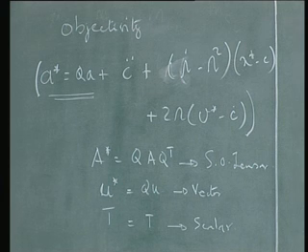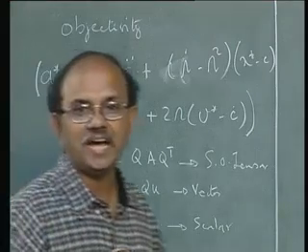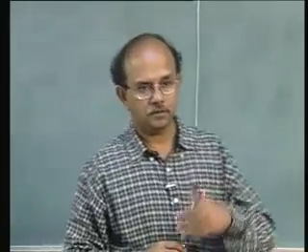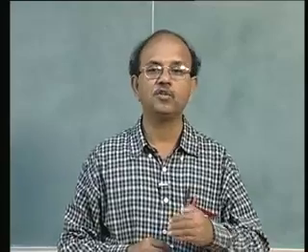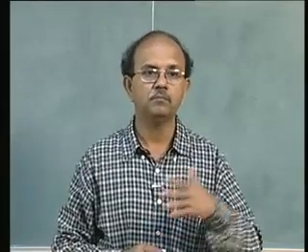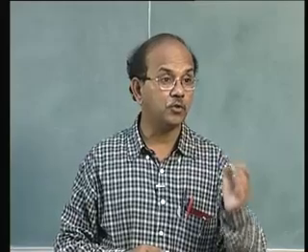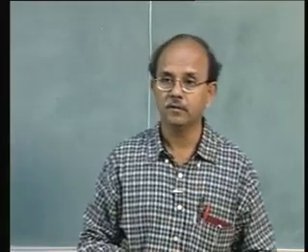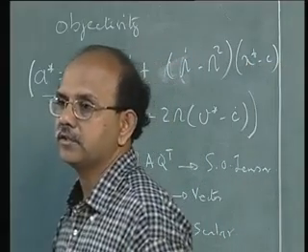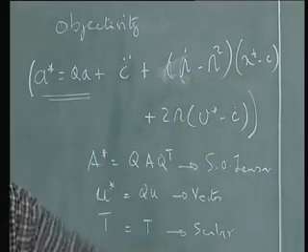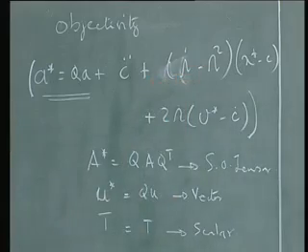In fact, if you had noticed, the major reason why acceleration is not material frame indifferent is because of the fact that both C and Q, both of them are functions of time. So in other words, we have allowed the second observer, the starred observer, not only to be different, but also to move with respect to time, and rotate, that is the Q, to vary that Q also with respect to time. That is very important. That is the reason why acceleration behaves in that fashion, and we recognize that some of them are known quantities. Say for example, this is the Coriolis component, that is the centrifugal force, and the other one is called the Eulerian acceleration, and so on.